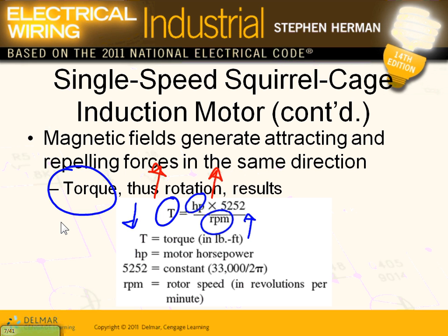If you want more mechanical work done, what do you need? A bigger motor, a bigger horsepower motor. So this concept is very, very important, guys. That's where you can convert torque into horsepower. The mechanical engineers take the torque and plug it into their own formulas so they can size all their mechanical equipment based on the torque that you have.